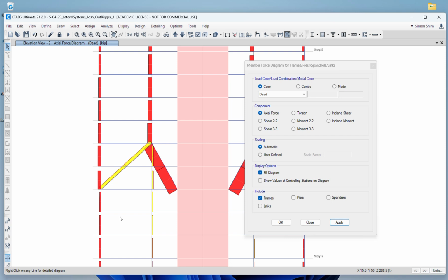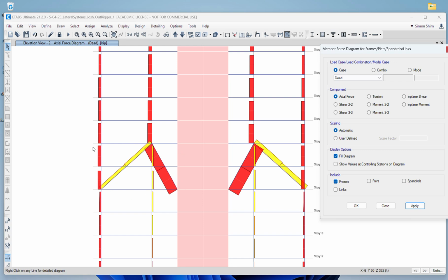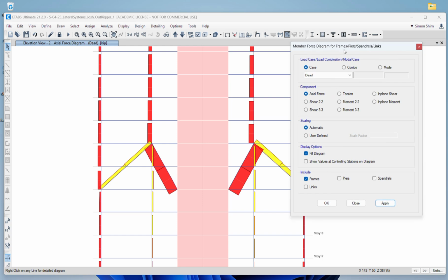This is just a mechanics and compatibility issue, because the finite element software modeling method basically depends on how you create it. Most of the time, one model cannot reflect all of reality, so you need to utilize a couple of versions to avoid any non-realistic load paths. This is the load we don't want for your final column design, right? Instead of these dead load cases, we switch to this construction sequence dead load.